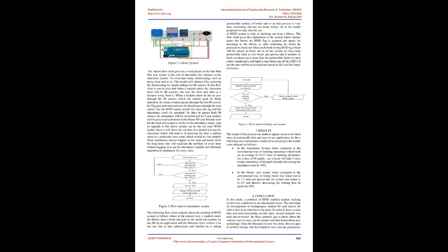And lastly, from the digital I/O ports there are pins from 9 to 13 making way to the RFID reader, RFID RC522. This is used to sense the tag from the books and the student ID while checking out from the library, where it will transfer the details to the micro SD card module for data processing and storage.